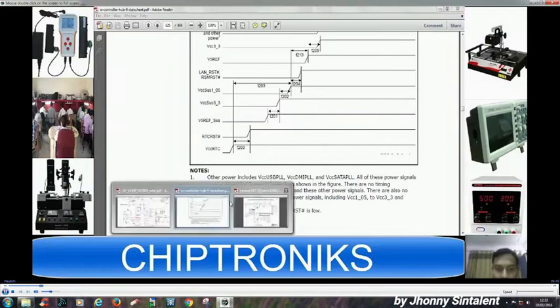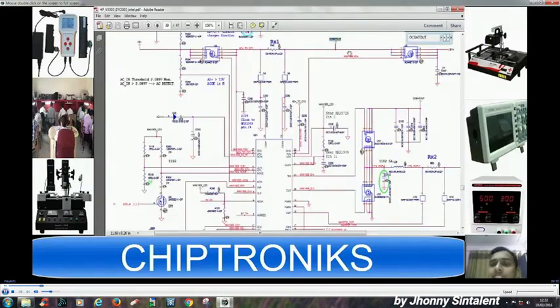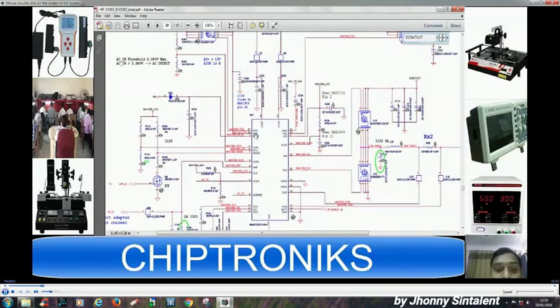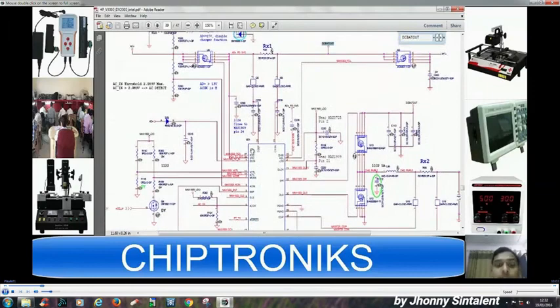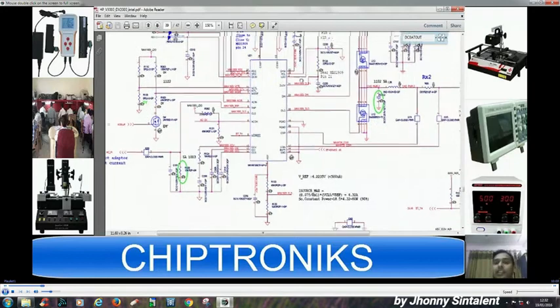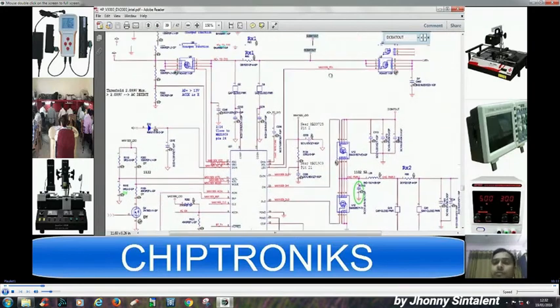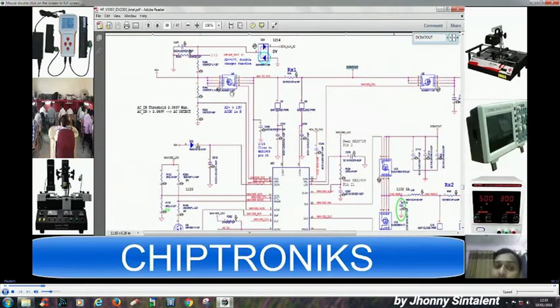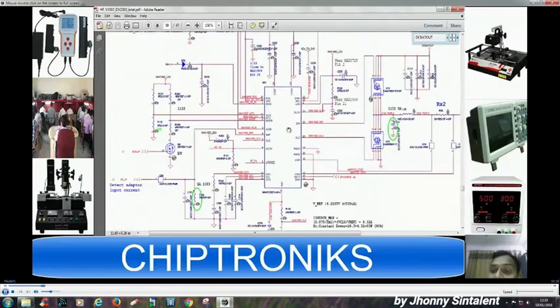So we have reached the place where, suppose DC bat out is not coming, then in that case we will check this MOSFET and this charger IC, that is we will check PDS, PDL, pull down source, pull down load. We have already discussed this in our earlier classes. Now we are using those concepts to study over here. So if DC bat out is not coming, then we have to check this MOSFET and this charger IC. So you will come to the correct place, right?